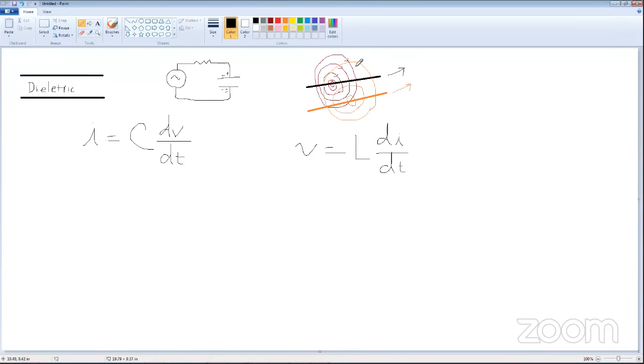Okay, so the final thing I wanted to show, here on the inductance side, is, like we mentioned, current flows in loops. So we have current flowing this way. Let's say from there it now goes down through the board, maybe through a via, and now it comes back to its source.